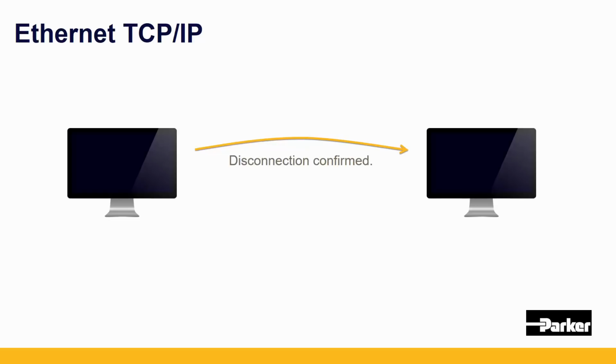Okay, so say with Ethernet TCP/IP, device A sends a packet to a slave and says, hey, here's the updated data, and I don't receive anything back from device B. Well, now I've just gone through a few servo cycles and finally device B goes, oh, by the way, here's finally my response from something that occurred 5 or 6 servo cycles ago. That's just not an acceptable way to operate our control scheme.